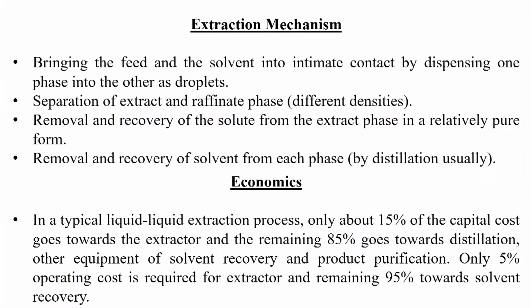Now, the third step, the most important step, is removal and recovery of the solute from the extract phase in a relatively pure form. The fourth one is removal and recovery of the solvent from each phase, that is from the extract phase as well as the raffinate phase. This is usually done by distillation, but there are many other ways also.